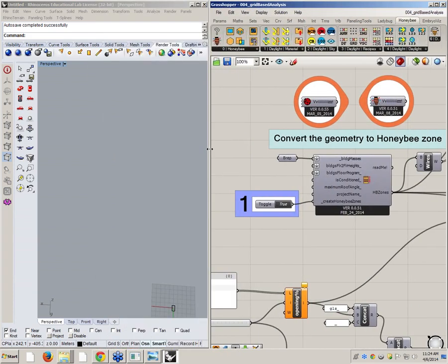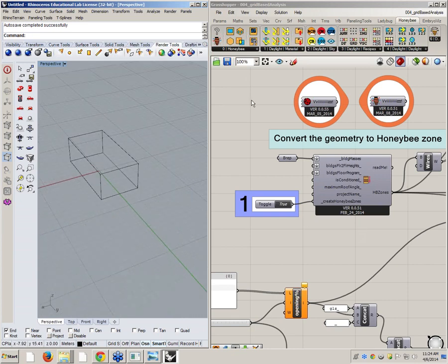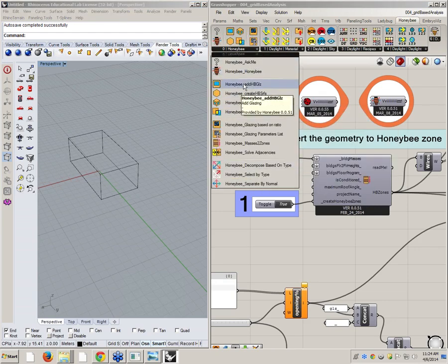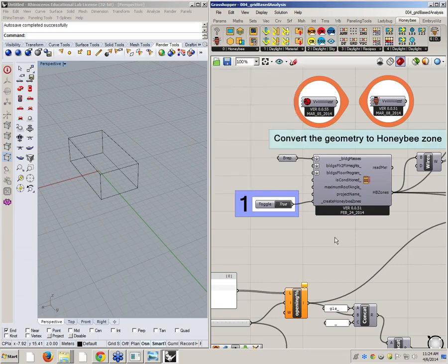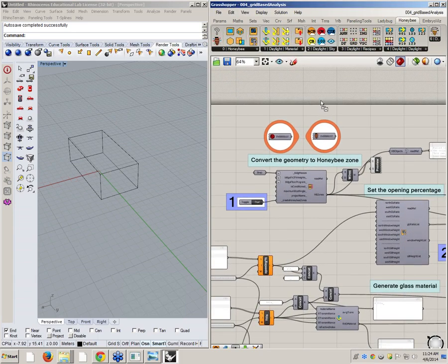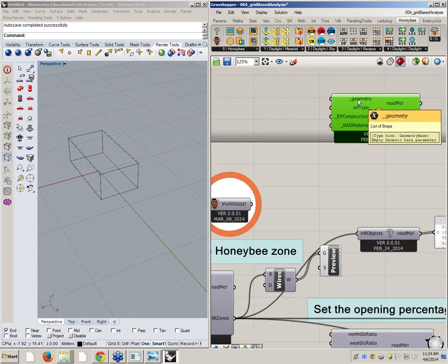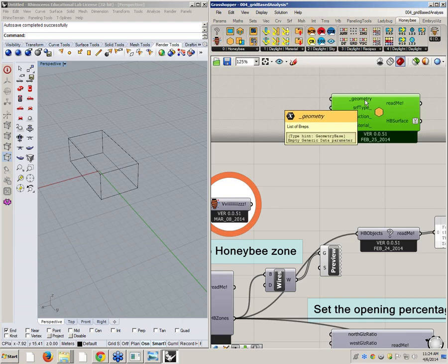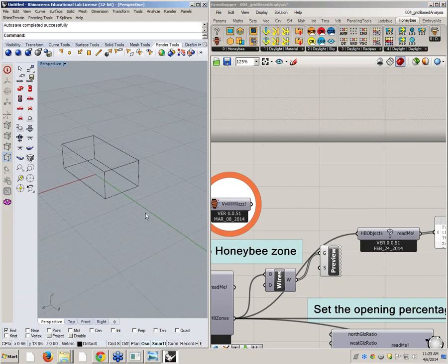So now I show you, instead of using a normal way of making a model like what we did, box and all that stuff, how you can use this panel, which is for preparing geometry in Honeybee. It doesn't mean you can't do it surface by surface. As we saw, you can use this component and have every single surface here and assign a Rad material, right? But sometimes you don't want to do this because it can be so much work, especially if you have a mass with so many floors. But now I show it for you for a single building.